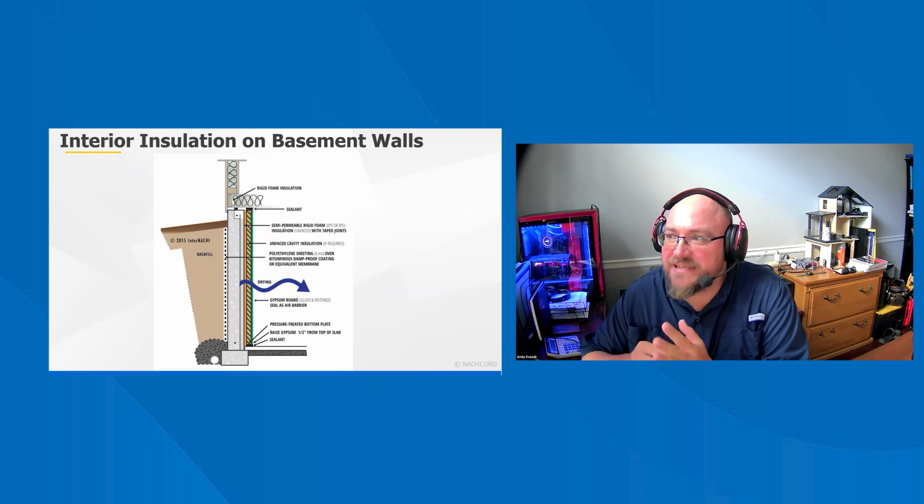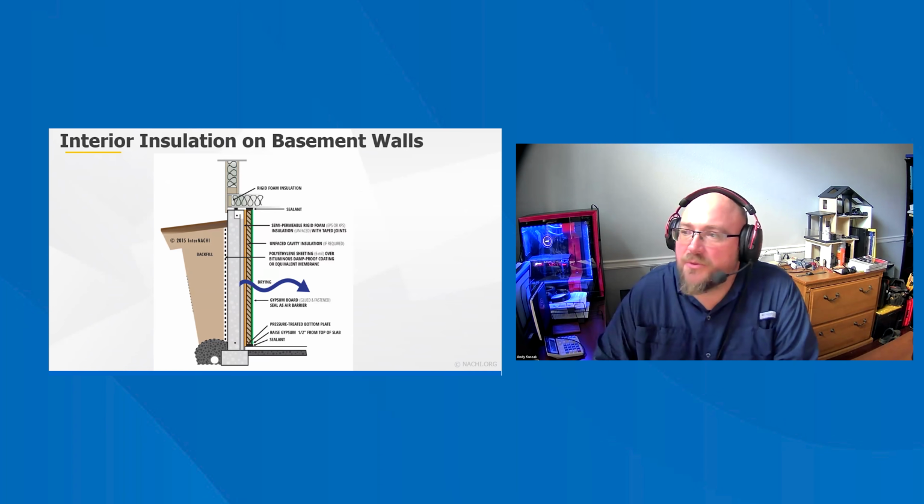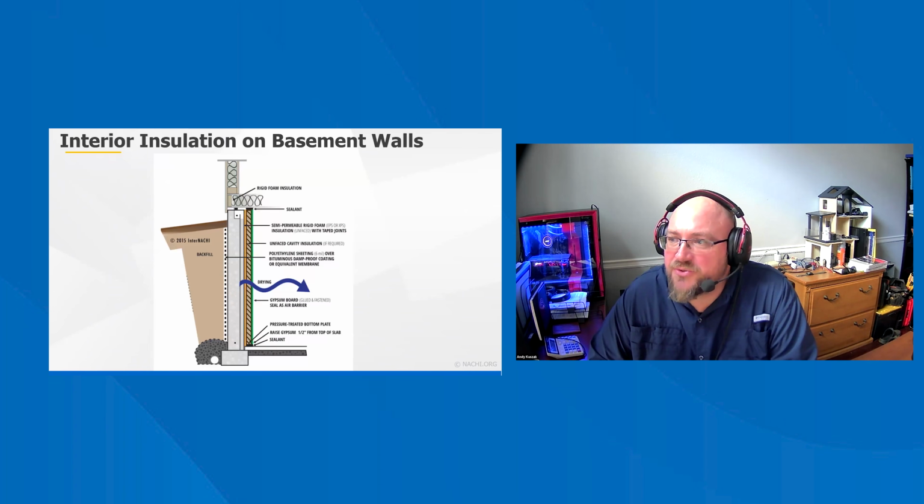A finished basement that is of high quality usually has some type of exterior waterproofing, relative humidity control in the basement, and air sealing. A dry basement is less likely to have problems with wood-destroying organisms. Once the exterior grading and groundwater factors have been addressed, the basement should remain dry and protected by properly installed wall assemblies.